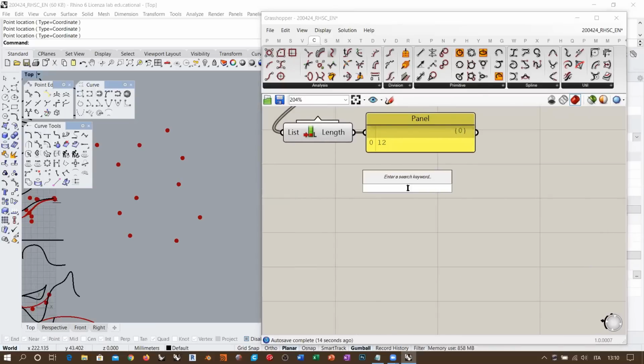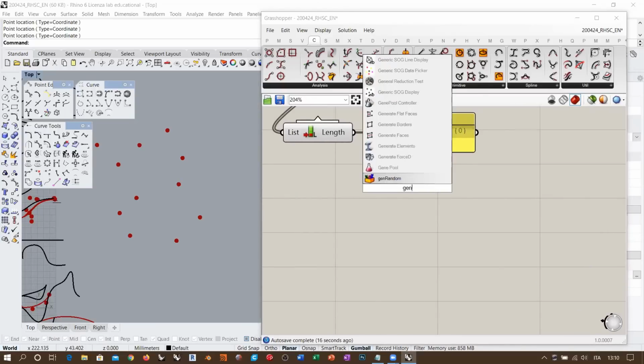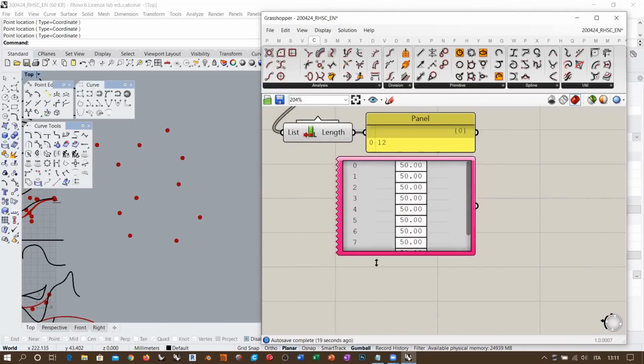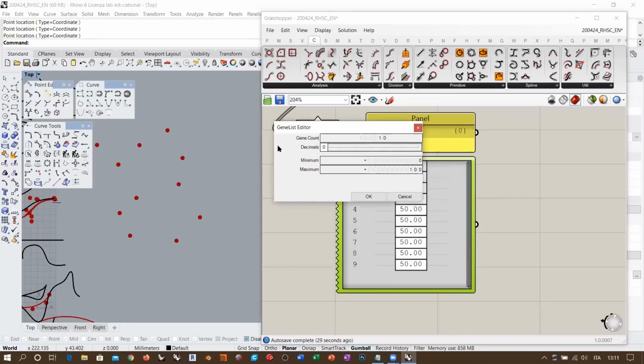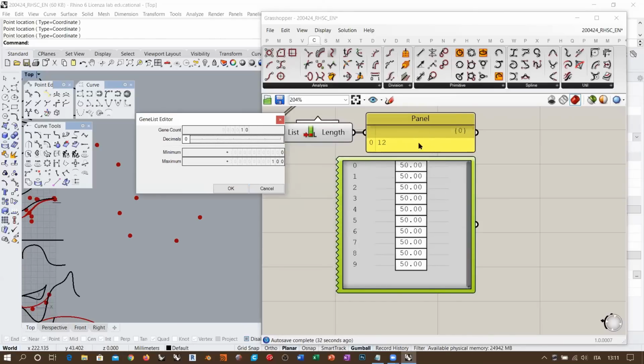So you go here and you create a gene pool, which is the more efficient way if you don't want to work with a complex set of sliders. This is basically one single set of sliders. You edit this, and let's get rid of the decimals because they are not necessary, because remember that Grasshopper always generates the normalized knot vector. So we only need to define how many genes, and we need 14 in our case, because it was 3 plus 12 minus 1, 14 genes, 14 sliders.